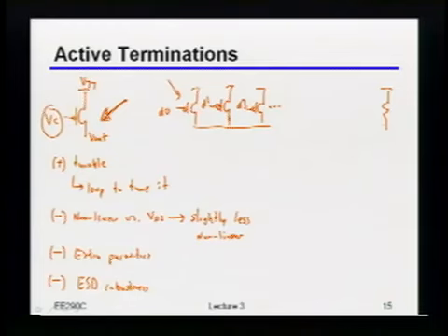Steven? Oh, I had a different response. Okay, well, let's see if we can figure it out from that. If not, we'll just go over to Steven and we'll see. It is actually related to what you said, by the way, but let's see if Steven gets it. My response is that now the tuning range of the PMOS active device is now smaller, so the linearity is better. Bingo, right.